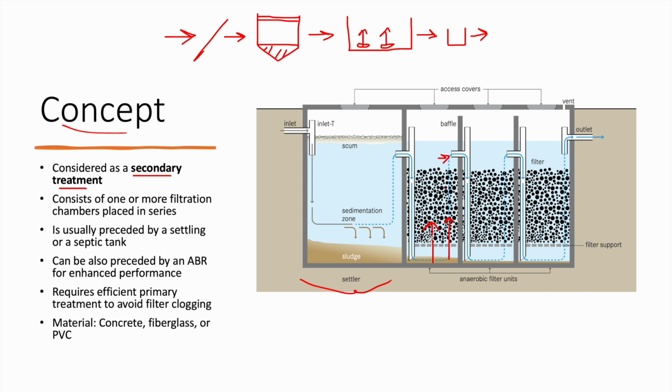Notice that this media is not placed at the bottom of the tank. It is somehow elevated. It is placed on a perforated slab. Notice this is a slab. It is perforated so that the water can enter through it, and it is placed at a certain height.